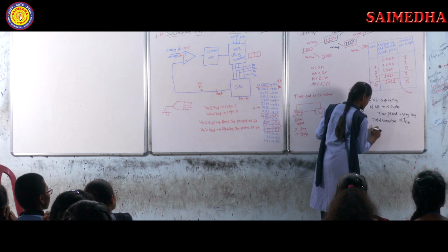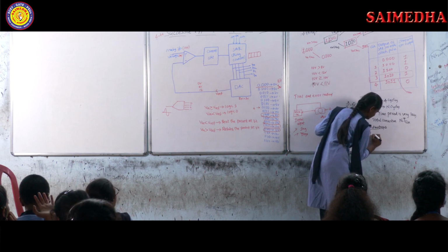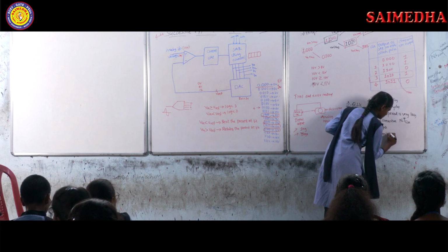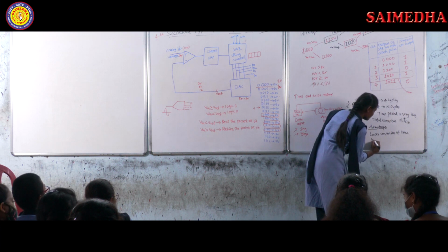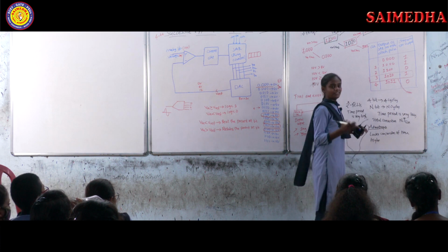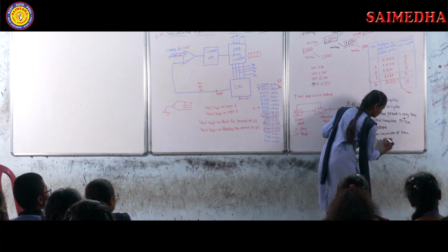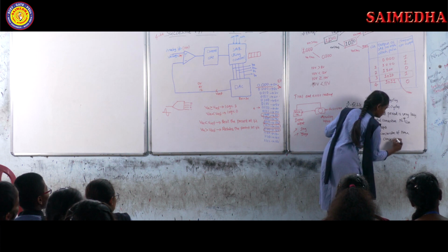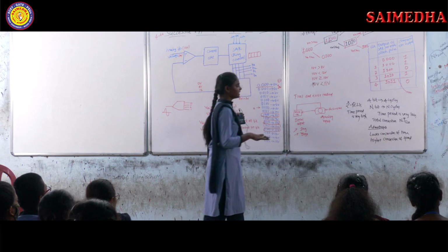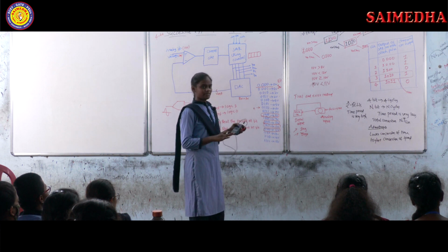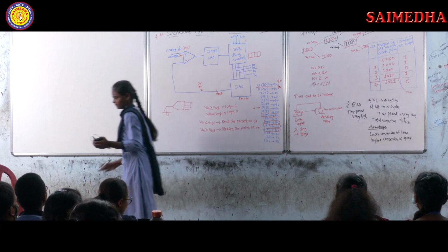So the main advantages of this are that it has lower conversion time and higher conversion speed, means whenever time is very less, then the speed of operation is also very high. So higher conversion speed. That's why the successive approximation register ADC method is widely used compared to the counter type ADC method. And let us go for the graph.